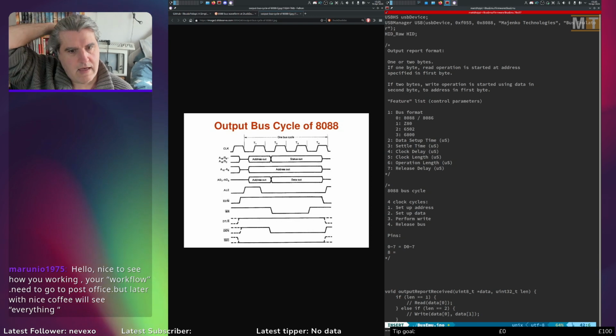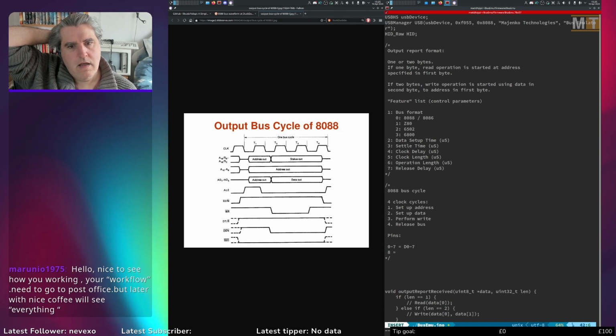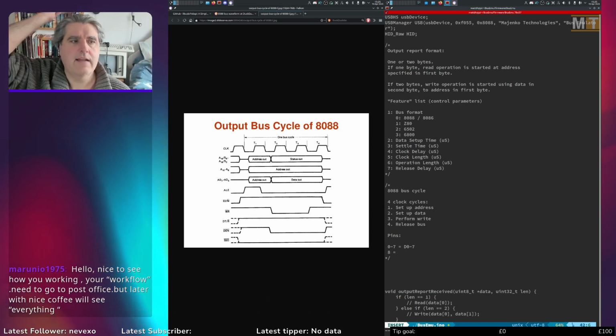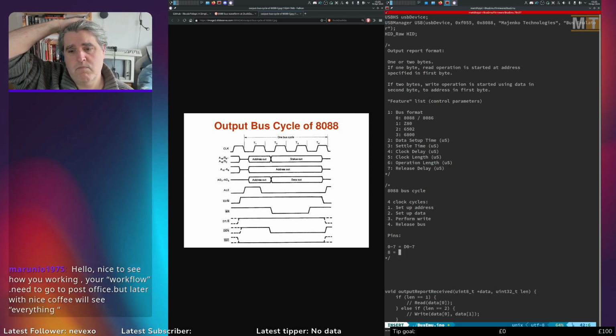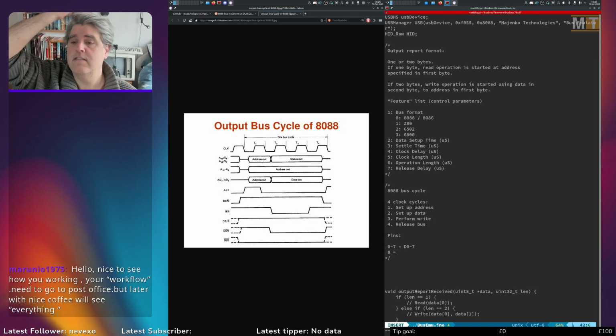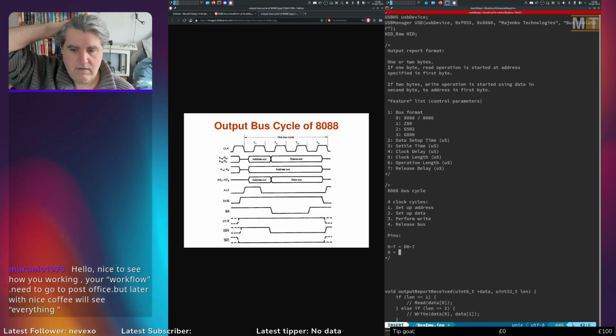I will have, or will I? No, I won't bother with a decoded chip select line, because I could theoretically just use any of the address lines and chip select lines in my operation.